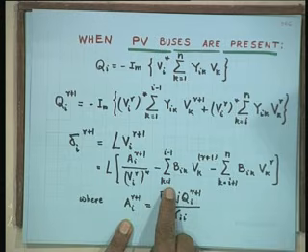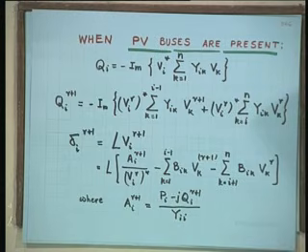Here Ai(r+1) is Pi minus jQi(r+1). Why Pi? There is no superscript, because Pi is known. Whether it is a PV bus or a PQ bus, P is common to them. That means P is always specified in load flow studies, except at the slack bus, where P is not known till the end. Now you know very well why it is not known till the end.